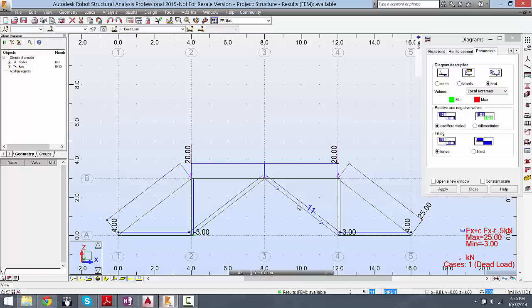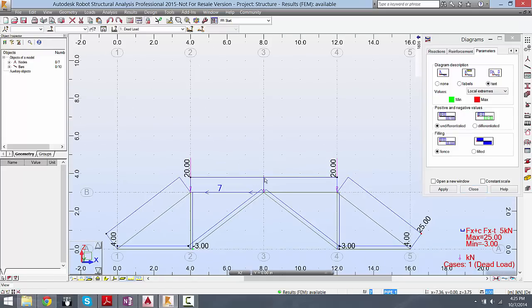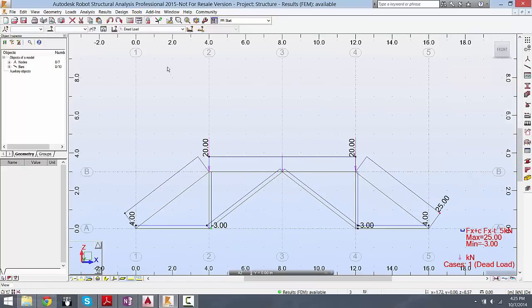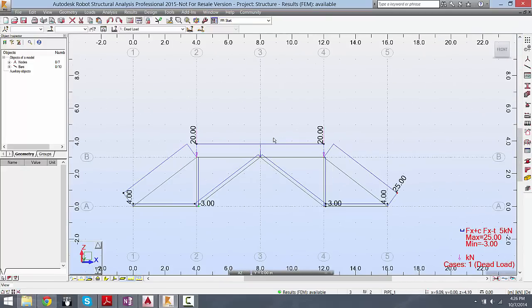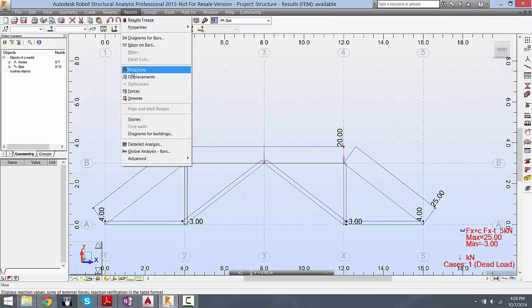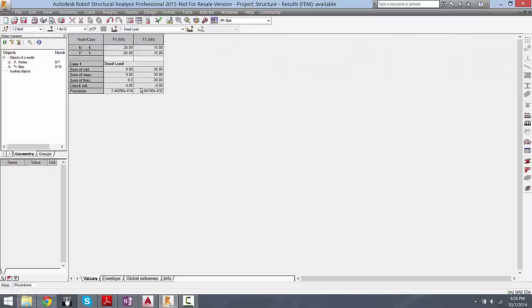And also what I'm accustomed to is having the tension be positive and compression negative. So just be careful with those signs whenever you're working on a project, so you know what's going on. You should be able to have an intuitive feel from any structural analysis that you know whether or not it's compressive or tensile.